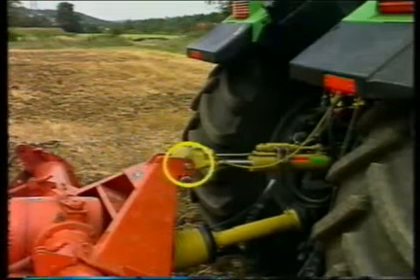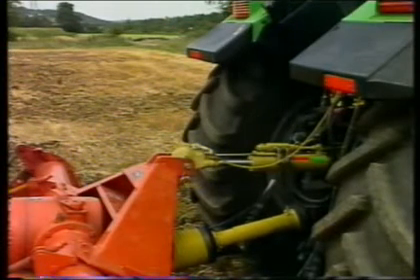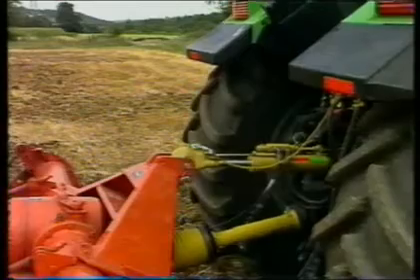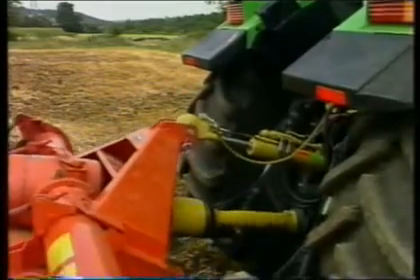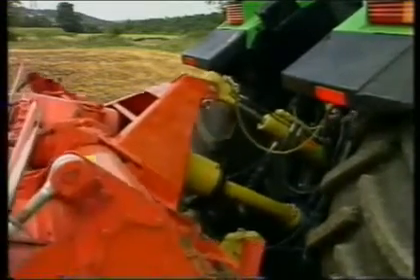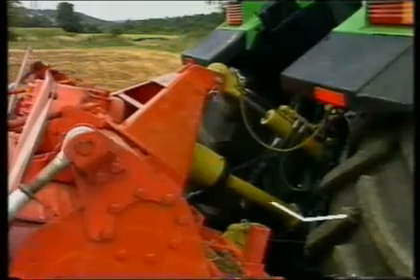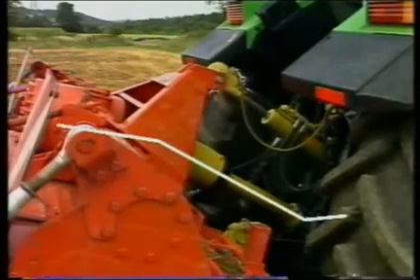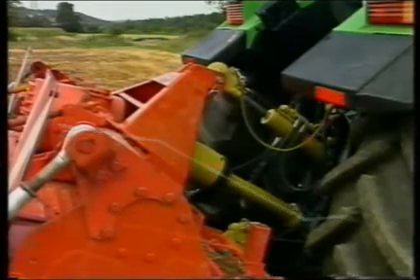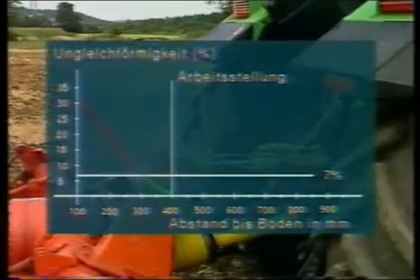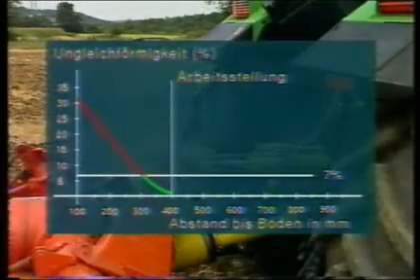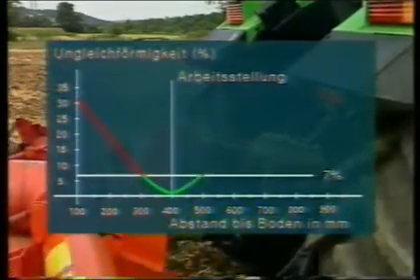Correctly attached three-point implements are parallel during lifting and can thus be driven with the PTO shaft engaged, even when turning. In the case of the so-called W-bend, too, where the imaginary extensions of the connecting shafts intersect exactly between the joints, the velocity variation is compensated for by the equally large working angles.